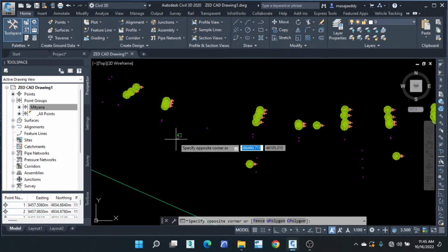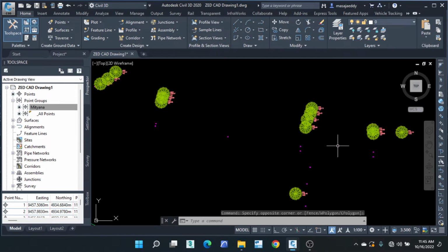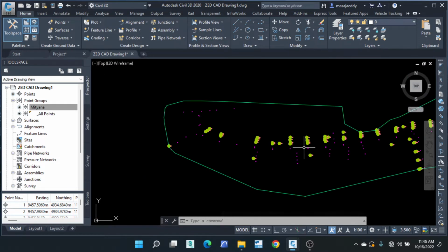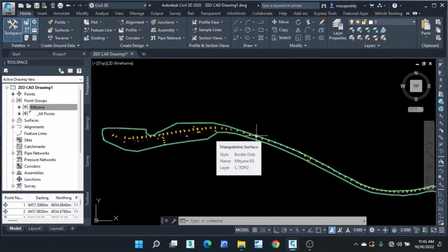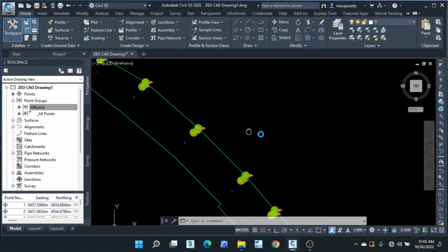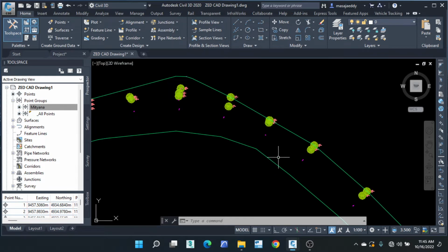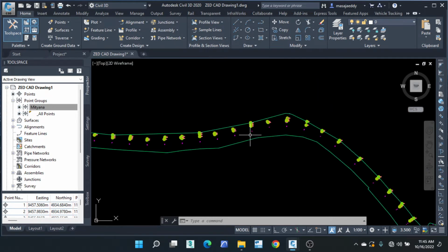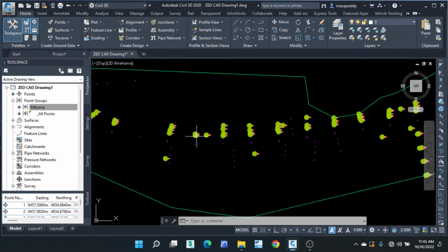So now once you only have your points for the center line, you can now gauge on these center lines to draw your alignment. I'm going to have Martin present the alignment and how we do our geometrical designs for the alignment, but may make a few changes for him to run his process of designing an alignment. In this case, it's going to be a plan view for our horizontal geometry. Okay.